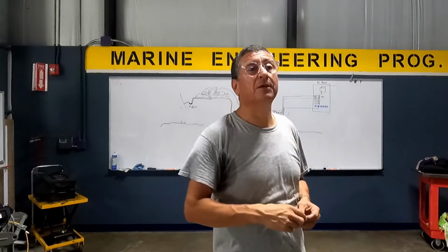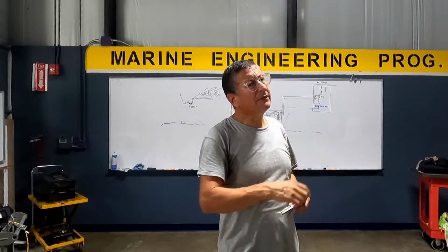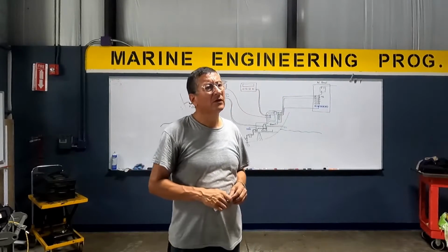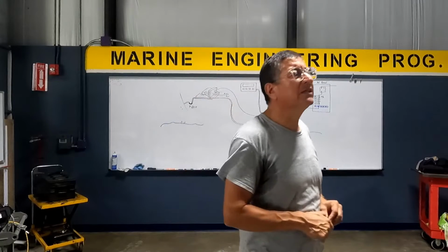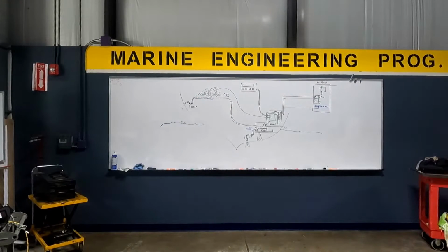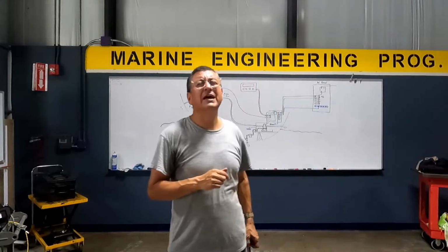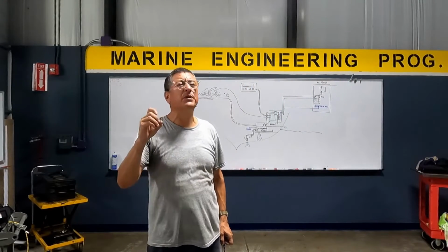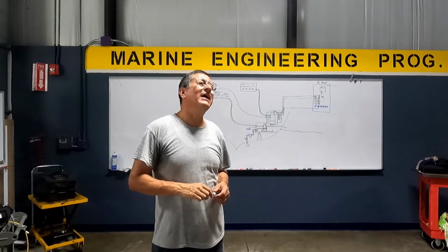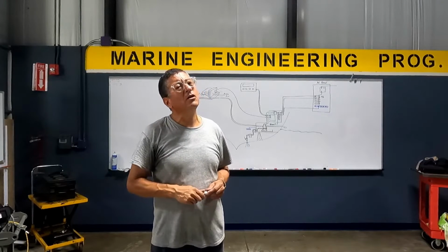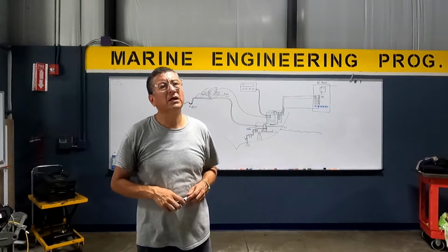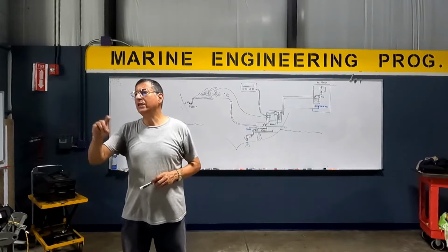You need to replace that filter periodically. Yeah, $10. What kind of what? Oh yeah, I don't remember exactly the name. It's an indoor coil spray cleaner. You buy it at Home Depot. You found it. That spray to clean those coils.